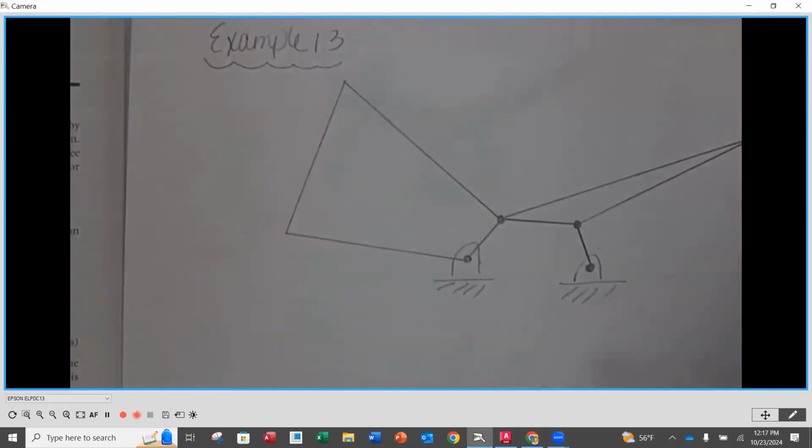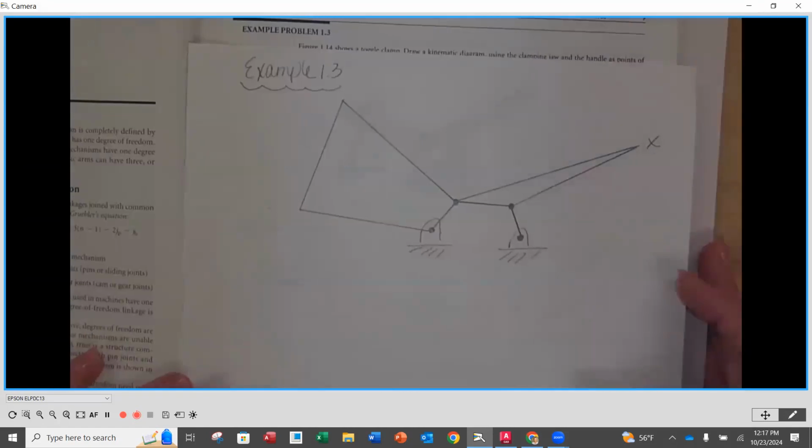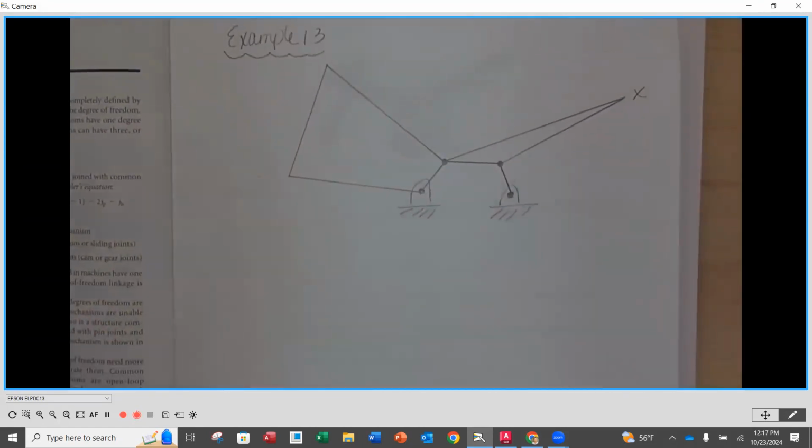Okay, the sketch that I came up with looks like this. So remember, a kinematic diagram is always going to be a simplified version of whatever our mechanism is. Okay, so it's just representing. So we're not putting details in there like thickness or even, sometimes, how the part looks. We have something very, very stripped down and simplified. So as we do our kinematic diagram, I'm just going to walk through the process of what I thought about as I was doing it.